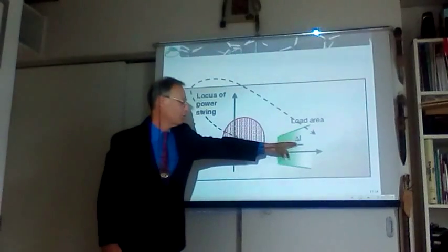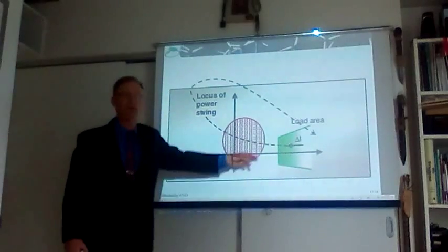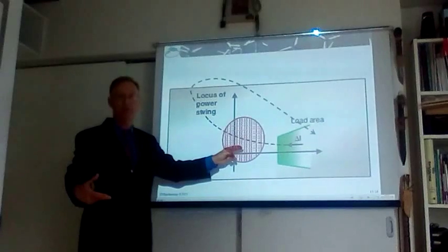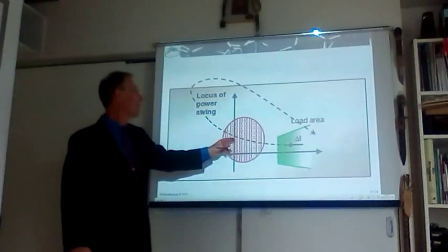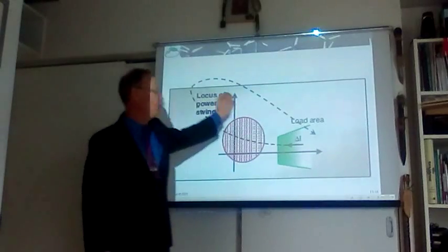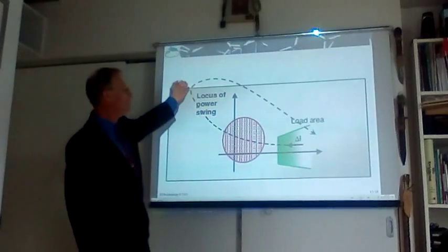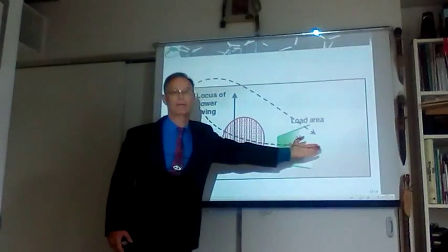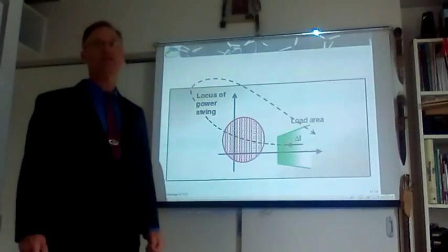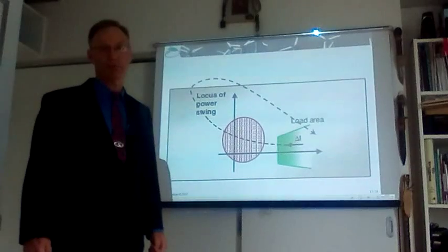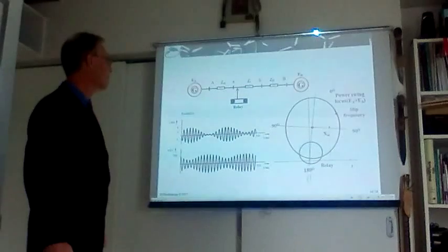And we will see the increase of current going sky high, going through the area where we have to trip, but it will not because it's happening slowly. And we will see that the current goes back. So the impedance is going down, down, down, and then up again. If the relay is identifying this case, it will not trip. And this is a power swing.